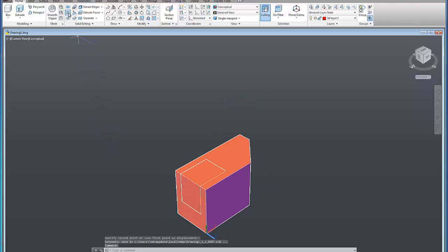Now we can use the subtract tool, selecting our original object shape, right mouse clicking, selecting the object to subtract. Uh-oh, another mispick. There we go. There's the object to subtract. Again, mispicks, shift, reselect. And I right mouse click and it subtracts that surface. So I can create really complex surface shapes and designs with it.